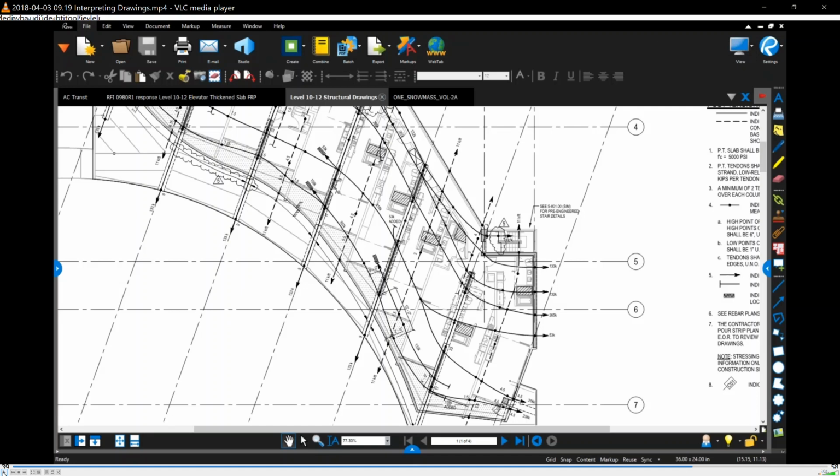You basically have a tendon that's not stressed yet, right? It's a certain length, and you're pulling it. The contractor will literally take spray paint, paint in a can, like aerosol, and they'll mark the cable where they have to stress to. So they'll pull to a certain length, and when they hit the paint mark, they know they're right about where they need to be. And so you're basically stretching that steel. So that's what a block out means, just like this. They just pull it up.